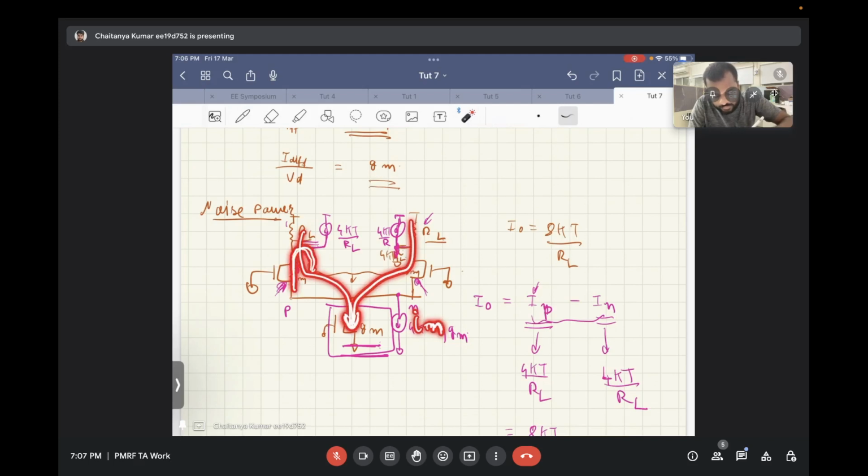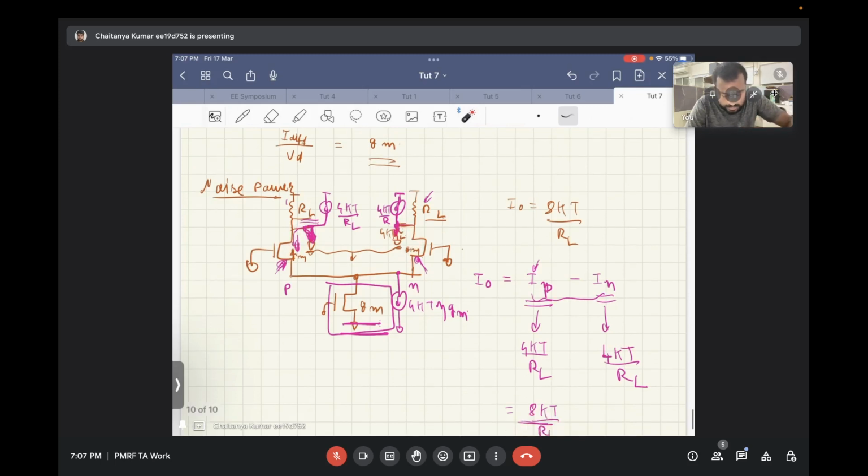Both will just come out of this short circuit that is present. Now this division has happened of a single, same random process. In previous cases, there were two different random processes going into the respective nodes. But now the same random process has been divided into two, and that is going into these P and N nodes. So they will be completely correlated to each other.